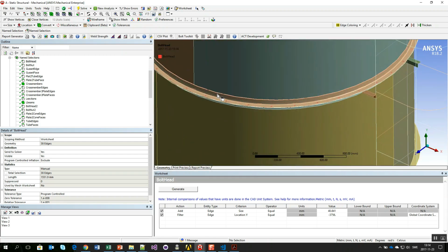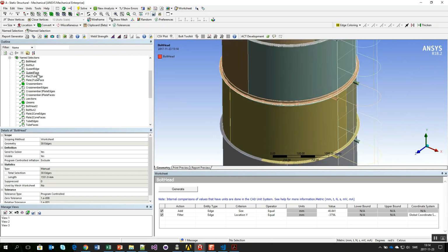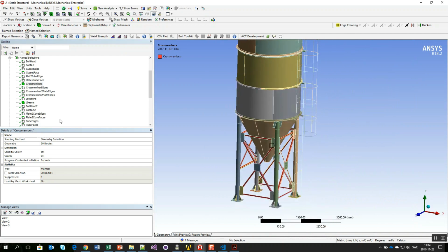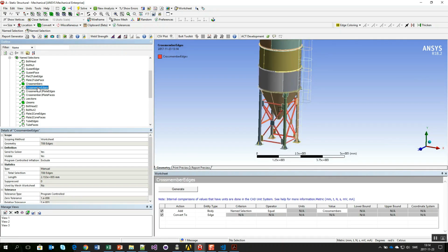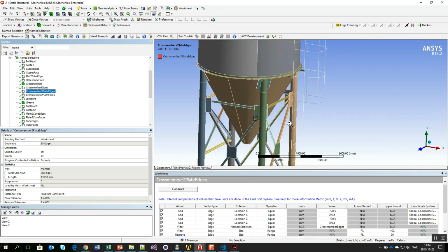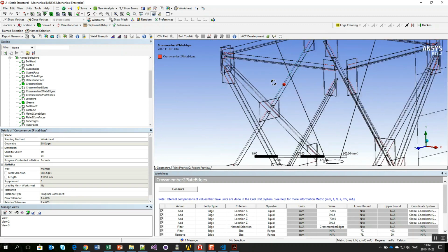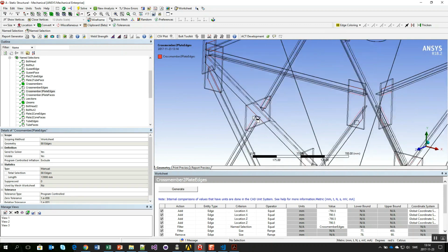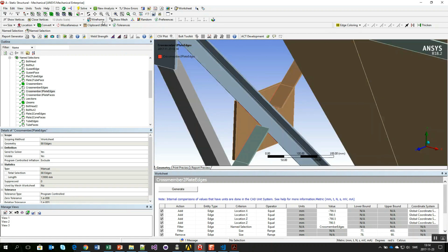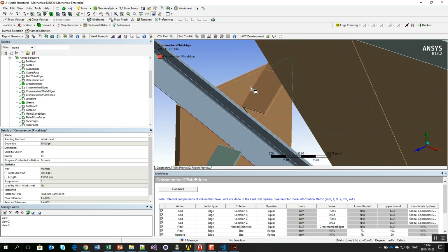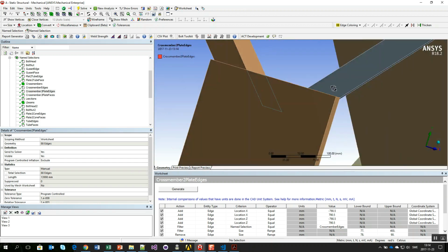So first I will show here I have a bolt flange where I will add some bolts, and then I have done, using these worksheet methods, for instance how I've selected the cross member, converted to edges, and filtered out all the edges needed for adding welds. So this also shows that I've done a face split in SpaceClaim to have an edge suitable for adding the welds here.